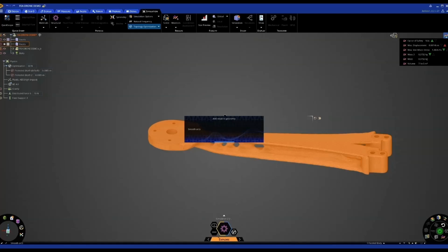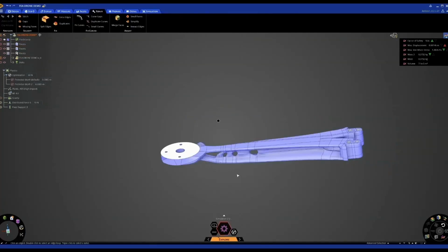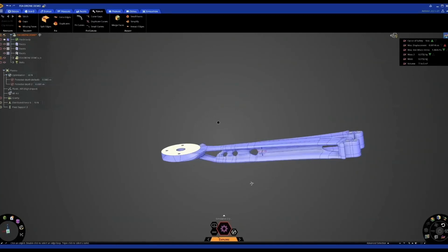So you can either export this out as an STL and potentially reverse engineer over it yourself, or you can let the software convert this back to a solid. Once this is complete, you'll end up with something that resembles this. So it is a patch surface model, but this can be exported as a step, a parasolid, any solid format you want. It is a solid body. So you'll end up with something like this that can be exported.